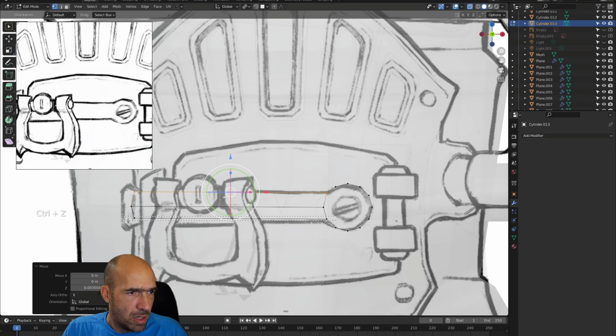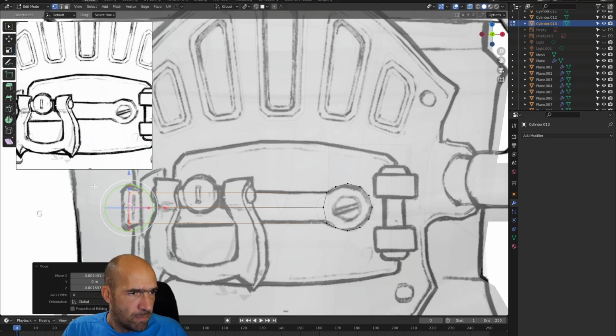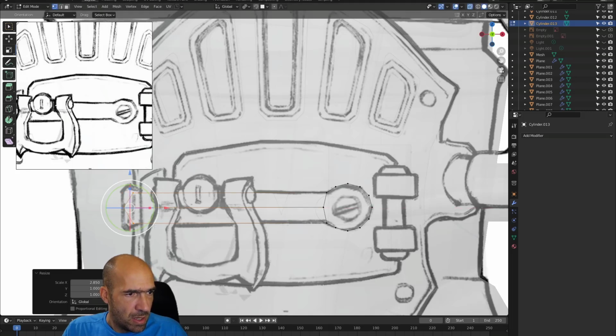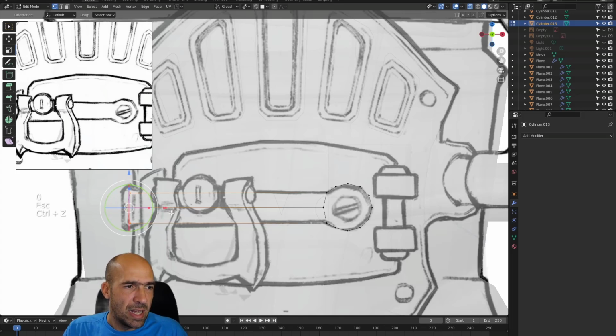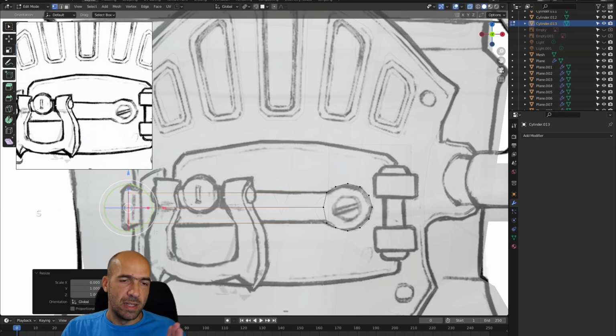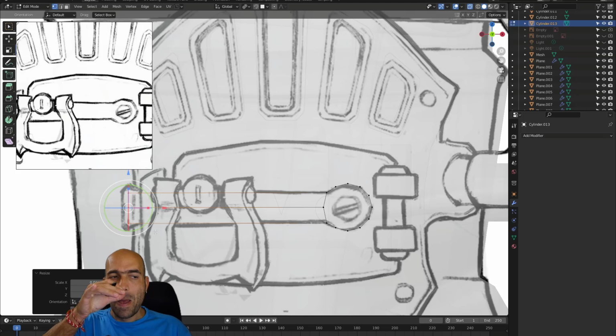This here, and this here. And this probably around this area. Let me try to scale again this. Yeah, I will scale, and then I'll press 0. No. Scale on x-axis 0. Let's break. S X 0. Yes. And this flattens it. I have to press the buttons: S to scale, X on x-axis, 0 to just flatten it. So I can flatten this one too, if I want.